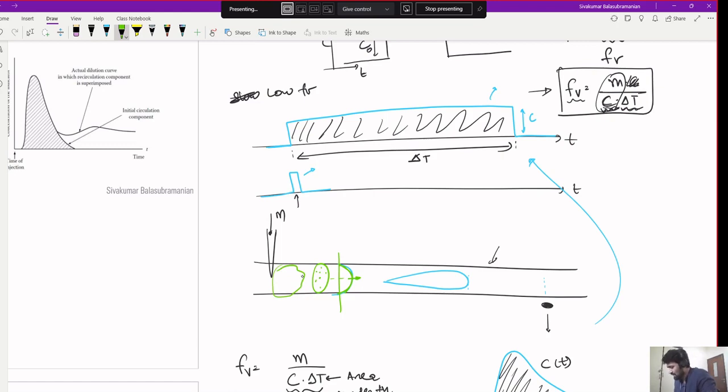Now, if you introduce the dye like this, the part of the dye that is close to the center of the tube will move at a faster velocity, whereas the parts near the walls will have a lower velocity. As this moves, there is more concentration of dye at the center and close to the walls of your tube, so they will start diffusing in. Over time, your dye will take a rough shape like this. Of course, there won't be a clear boundary; the boundary will be hazy, but in general it'll take a shape like this.